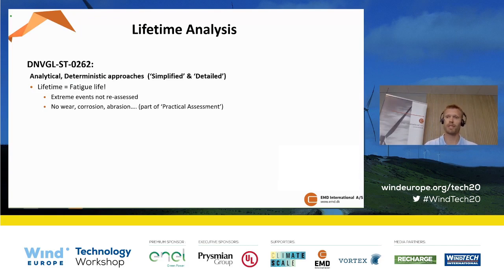So one thing I first need to emphasize is that when I say lifetime, I mean fatigue life. And so things like extreme events are not reassessed according to the DNV-GL standard, and wear, corrosion, abrasion are all part of the practical assessment of the wind turbine. So they're not accounted for. So lifetime in this context is fatigue life.